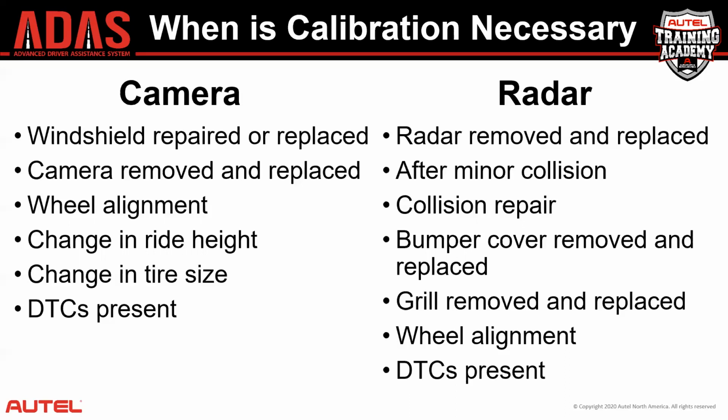So in this particular vehicle that hit a pothole, knocked it out of alignment, where the vehicle is driving is no longer where the vehicle is pointing. Over time, the camera begins to learn this and it adapts to it. We perform the alignment, we correct the alignment issue. Now the camera has compensated and will be overcompensated in the opposite direction if we don't calibrate it. Now, will it eventually learn? Maybe. However, if you don't properly calibrate a vehicle after an alignment, you or your shop could be held liable.